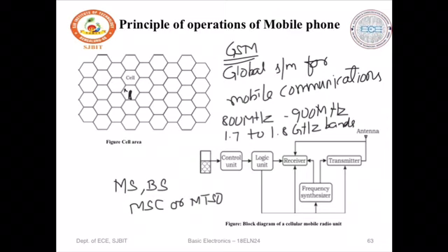The transmitter's span of coverage is called a cell. As the cellular telephone user moves from one cell to another, the telephone must be effectively passed on to the local cell transmitter. Basically, a cellular mobile phone has three sections: RF section, analog baseband processor, and digital baseband processor.